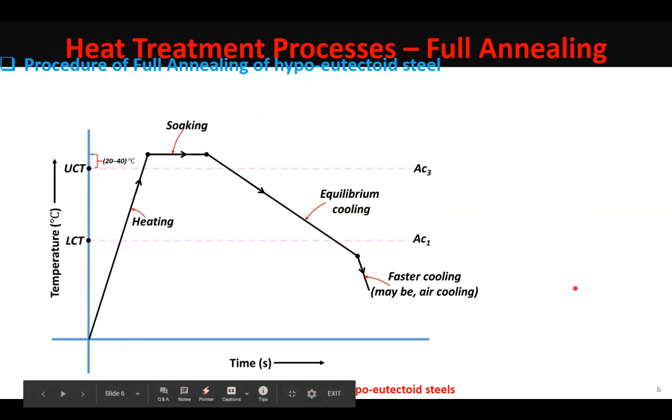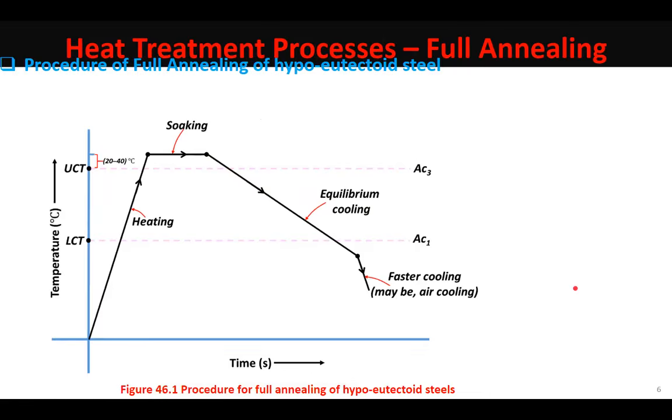And again, the cooling rates that would be achieved by the steel components would be somewhere around 15 to 20 degrees centigrade per hour, or 10 to 15 degrees centigrade per hour. And with experience you would come to know the time, and you can note from the CCT diagram that if I had taken my steel to this temperature, followed this type of cooling rate, after what amount of time steel would have cooled to a temperature below its lower critical temperature.